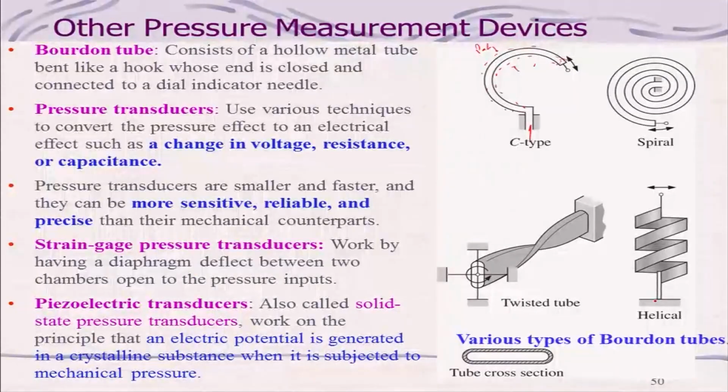That is known as a piezoelectric transducer, right? It can take a higher amplitude of pressure and also sustain a larger frequency. Therefore, in your IC engine, the piston cylinder engines you use in your car, where we want to measure pressure, we have to use piezoelectric transducers.